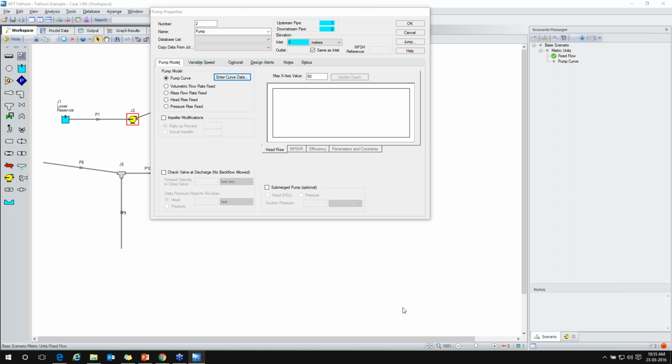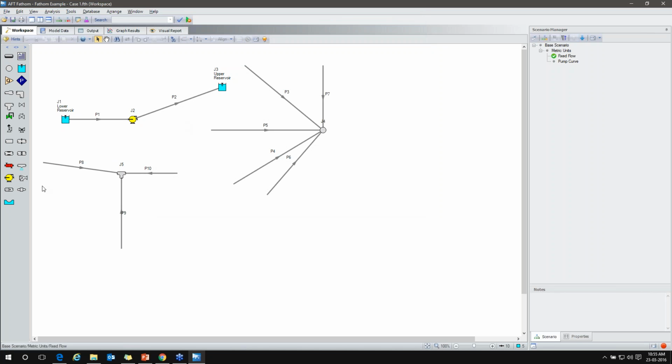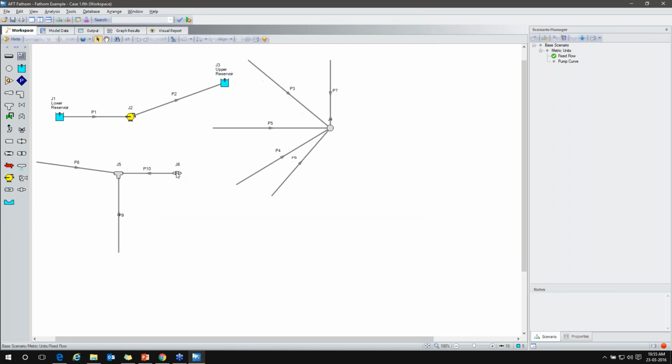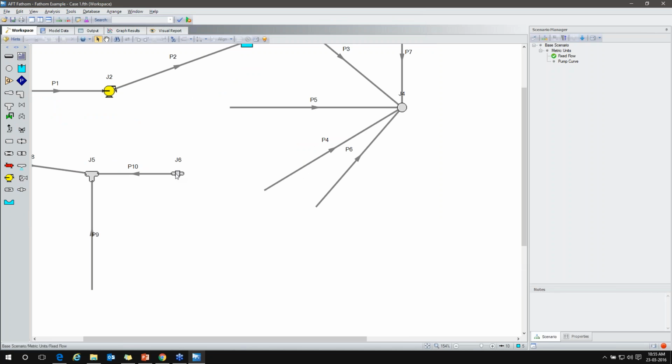How to add a fixed pressure drop? Okay, so for adding a fixed pressure drop into the case, we can model the system as a resistance curve, or if there is any specific component which you would like to model as a fixed pressure drop, that can be done over here. We have an option of general component, the last option. This general component can be used in all those areas where you don't have a specific component available in the toolbar, and that is creating a pressure drop into the system.